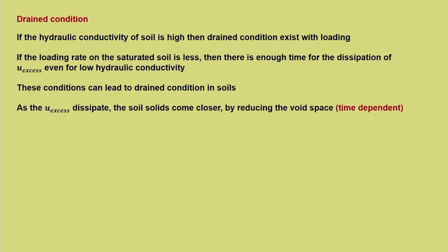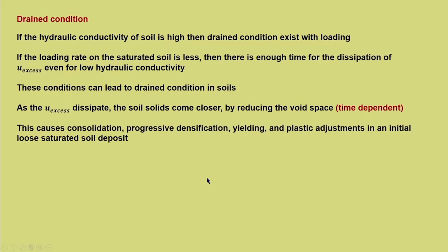Now, that adds complexity to the behavior of cohesive soil, whereas in the case of cohesionless soil, it is an instant response and drainage is also more or less instant. So, you do not have to wait to see its final response, but that is not the case with cohesive soil. It is time dependent, and what time, in what manner, we do not have any clue at the beginning. So, it depends entirely on the soil characteristics. This causes consolidation, which we know.